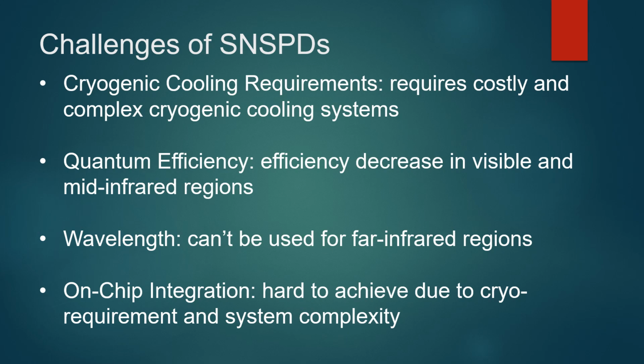And lastly, some of the challenges of the SNSPD. First of all, its cryogenic cooling requirement. SNSPDs must be operated at very low temperature, typically below 4 Kelvin, to maintain superconductivity. This requires a costly and complex cryogenic cooling system, which often uses liquid helium or closed-cycle cryocoolers.